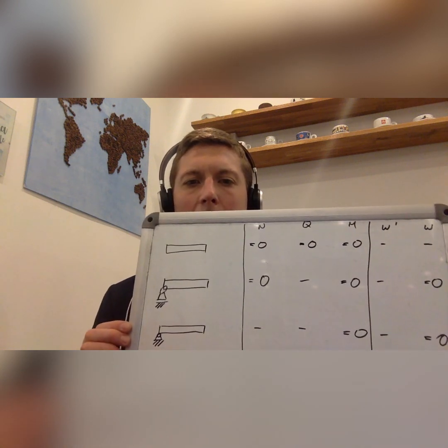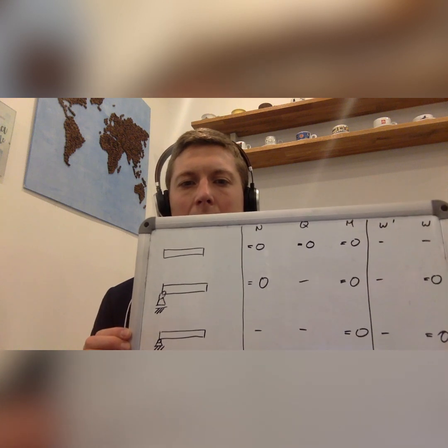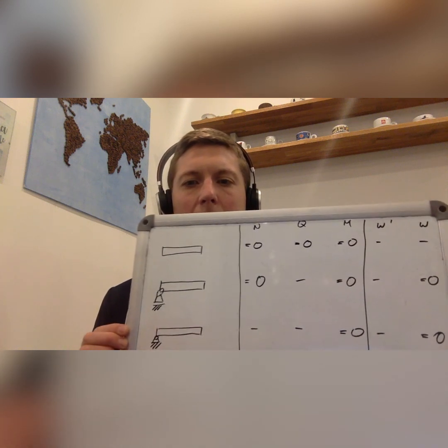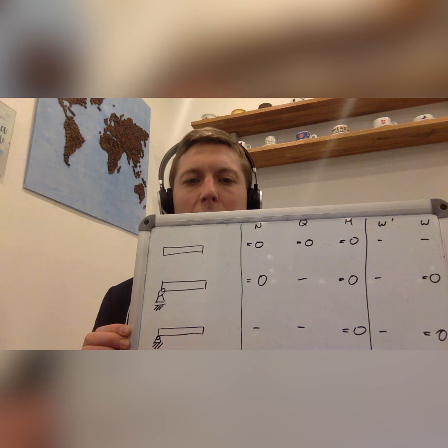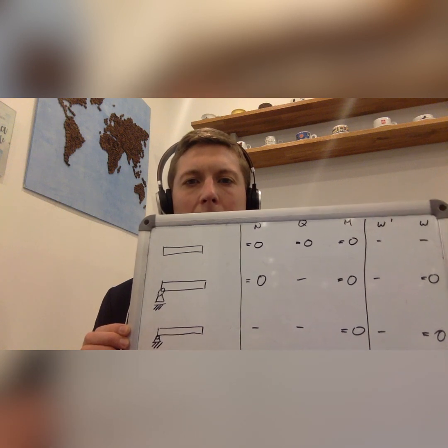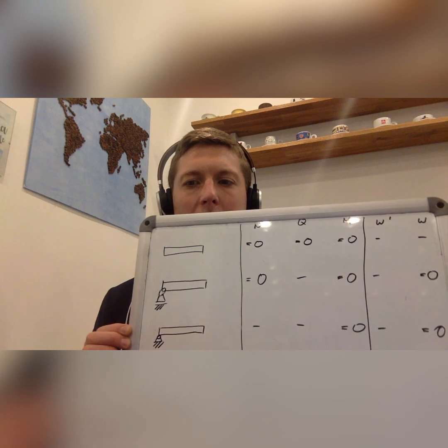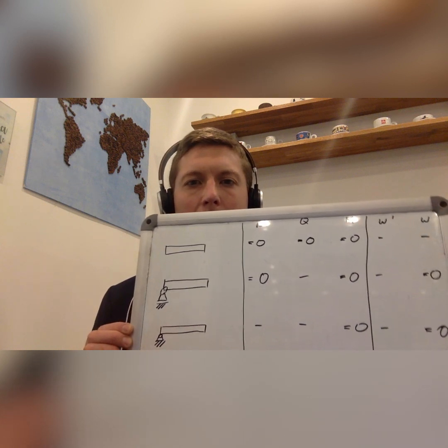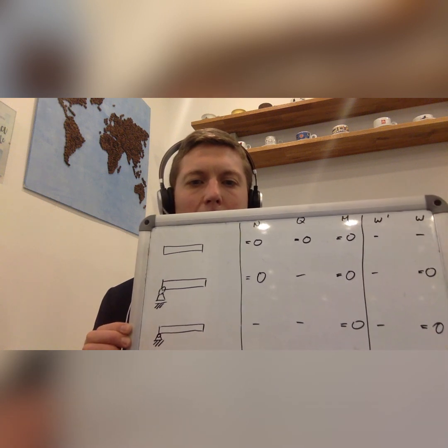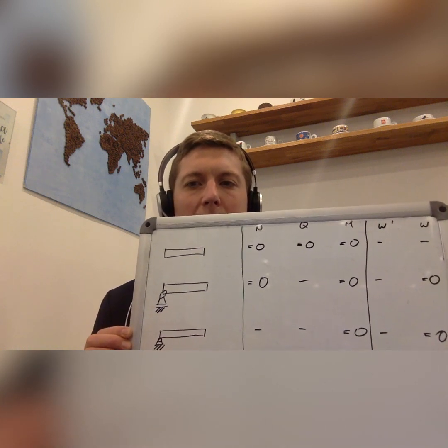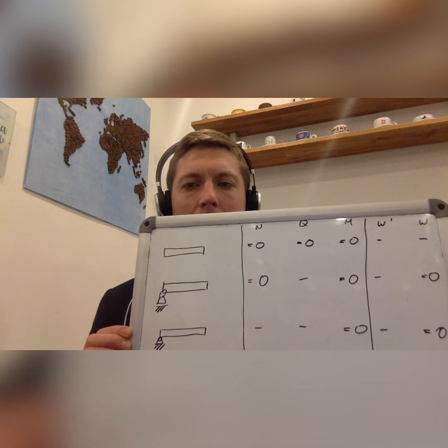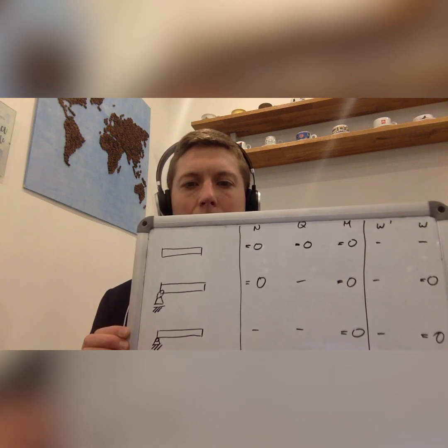And for the kinematics, compared to the loose bearing, it's identical. So the position remains at the c coordinate position, so w equals 0, but still there is the possibility that we have an inclination of our beam at this position, and therefore this w prime is not equal to 0.